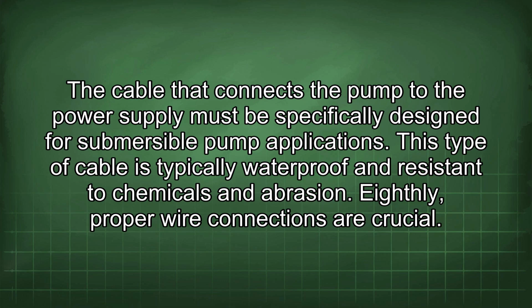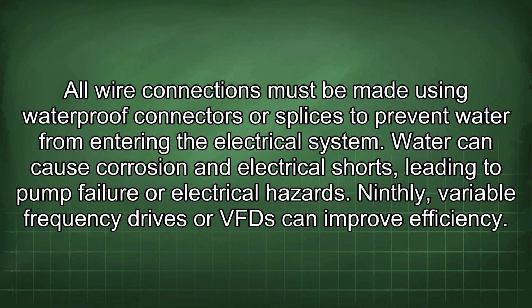Eighthly, proper wire connections are crucial. All wire connections must be made using waterproof connectors or splices to prevent water from entering the electrical system.